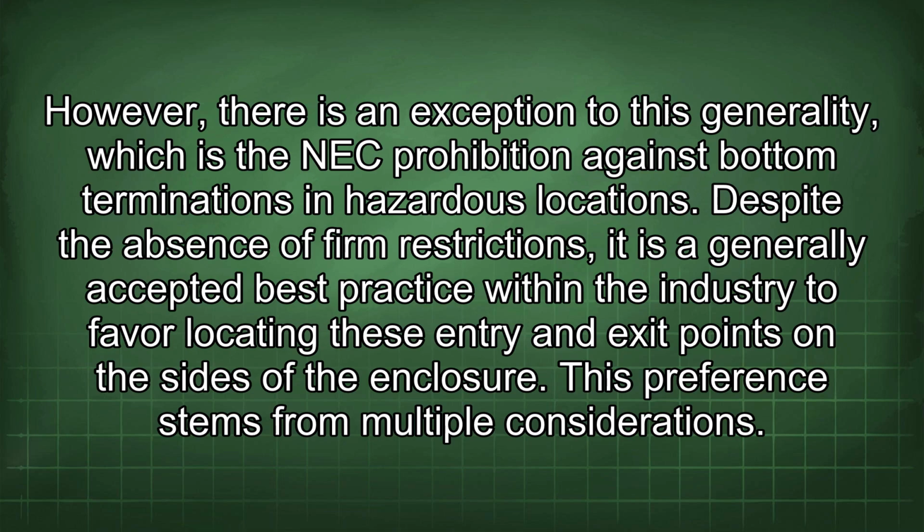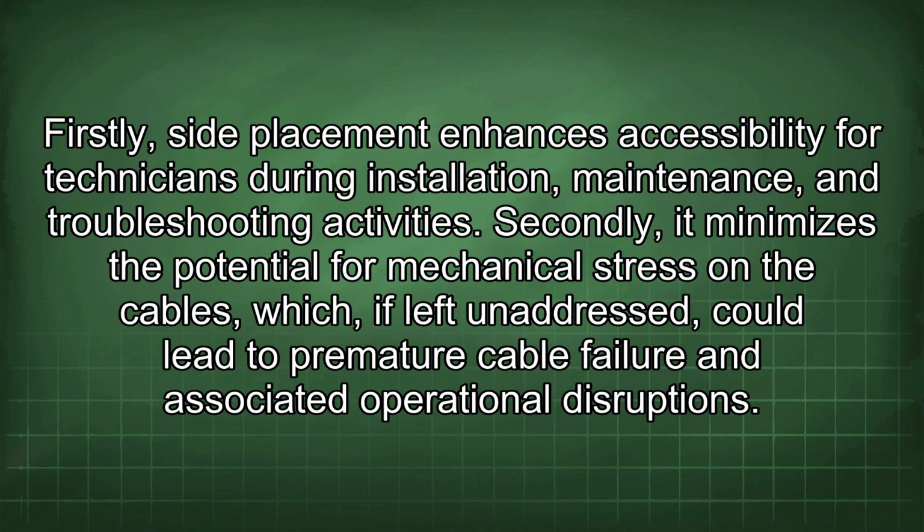This preference stems from multiple considerations. Firstly, side placement enhances accessibility for technicians during installation, maintenance, and troubleshooting activities. Secondly, it minimizes the potential for mechanical stress on the cables, which, if left unaddressed, could lead to premature cable failure and associated operational disruptions.